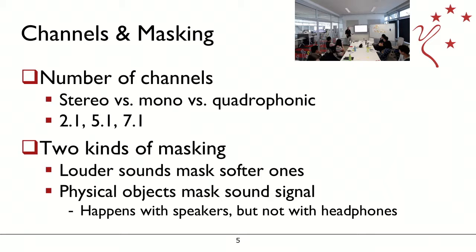In general, people are very good at localizing these mid to high frequencies, and we're really bad at localizing low frequencies. So the 0.1 is typically a big woofer that's put somewhere in the corner, and it doesn't matter that it's in the corner because you won't be able to tell where it is anyway, but I can put a lot of power into it because it's a big unit. Whereas I can put smaller speakers around, and that will allow me to better utilize the space and still allow people to localize where something is coming from.